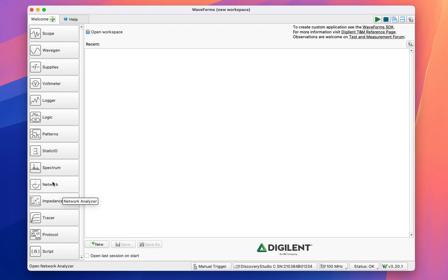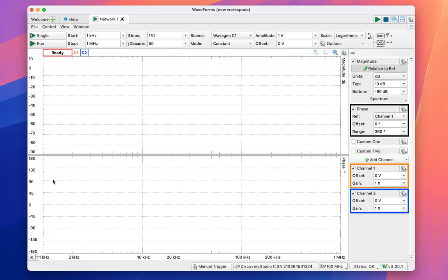So we're going to go to this network analyzer tab. We're going to open this network, and we have plenty of options. Let me walk you through this problem. First, we need to define the span of the frequency sweep. In this case, we're going to go from 1K to, let's say, 10 mega. That means we're getting 37.5 points each decade, right?